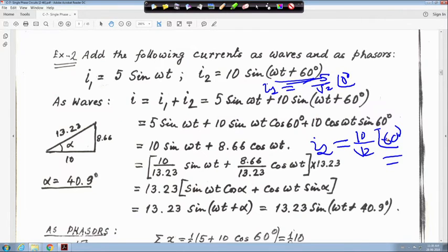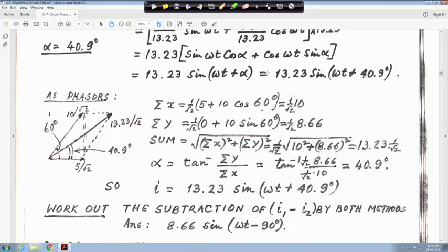So, when you solve, unless and until it is stated otherwise, if any term is attached with this sine term, that means it is a peak value, and you have to divide it by root 2 to take the RMS value, because all our calculation later will be based only on RMS value, right. So, in this diagram, this 5 by root 2 angle 0 is the reference one. Another one, I told you, is 10 by root 2, and this is 60 degree, right.